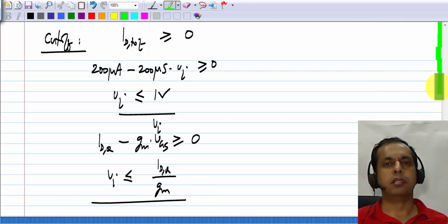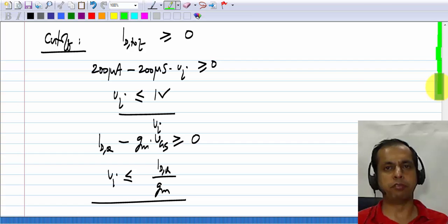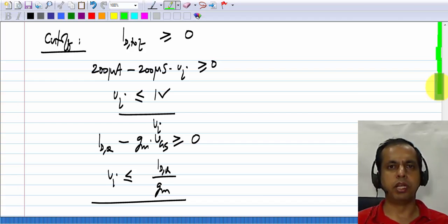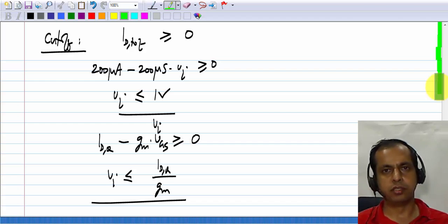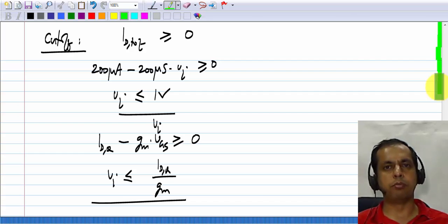In summary, the small signal picture of NMOS and PMOS common source amplifiers is the same, and this is true of every other type of amplifier. If you look at NMOS and PMOS, small signal wise they will be the same, large signal wise they will be different. The swing limits in particular are the opposite. If in some circuit saturation imposes an upper limit in the NMOS amplifier, it will impose a lower limit in the PMOS amplifier, and similarly for the cutoff.